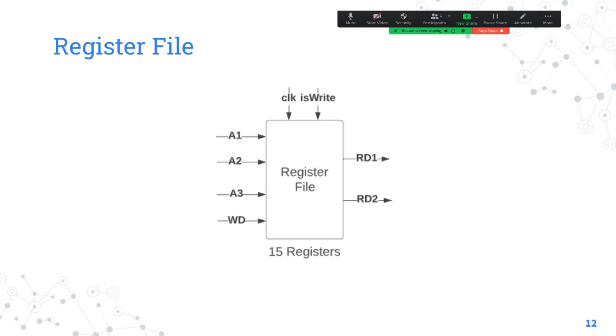The working of this may look something like this. The control unit is an FSM, basically a finite state machine, so it would transition to different states. Like you would have learned in the pipeline part of the CO course, let's assume there are 5 stages, though an ALU operation has only 4 stages; there is no memory stage. Let's assume we have an ALU operation. The first stage would be the fetch stage. The second stage would be the decode stage.